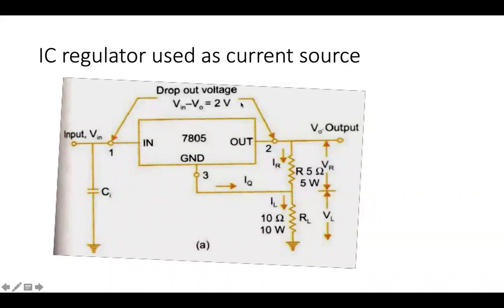Here this IC may not have billions of transistors, it might have a few transistors, a few gates, but these delays, these drops across each transistor will add up, and finally at the output side you find about 2 volts of drop compared to your input side. So that's why when we give an input, we try to give it about 2 volts higher.